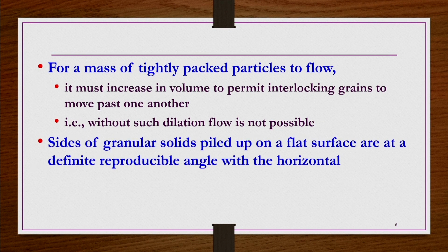Then, the sides of granular solids piled up on a flat surface are at a definite reproducible angle with the horizontal, and this reproducible angle is known as the angle of repose. Right. So, you can do this experiment. You take wheat and then you take rice, and you pour them carefully on a horizontal surface. Whatever the time you pour it, these sides form a piling up like this.